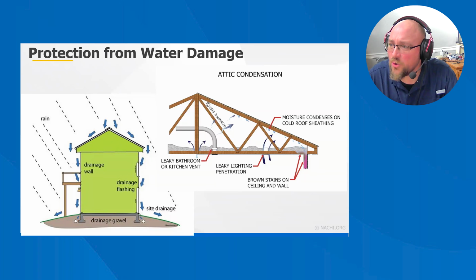So, quick action if water intrusion occurs. Water shutoff valves should be readily accessible and identified so that the water supply can be easily turned off in the event of a plumbing leak. If water intrusion does occur, damage can be minimized by addressing the problem quickly and thoroughly. Inspectors should help their clients identify all water shutoff valves.